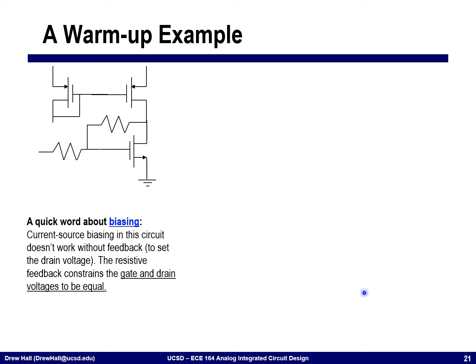All right, so to set us up for this, let's look at this example that I'm showing here. Resistive input, resistive feedback. Instead of showing this with an op-amp, I'm now trying to implement this as an integrated circuit. And so I have an NMOS transistor here. I have a current mirror that I'm using to bias this transistor. Okay? And so my amplifier here looks something like this.